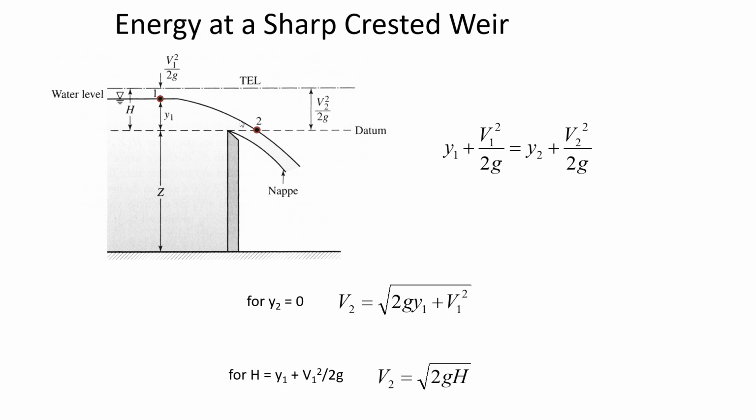And this is actually very similar to the discharge from an orifice, the equation that we've seen before, the square root of 2gh, because the height of the specific energy here is partly elevation above the datum, so the water depth, and partly velocity head.